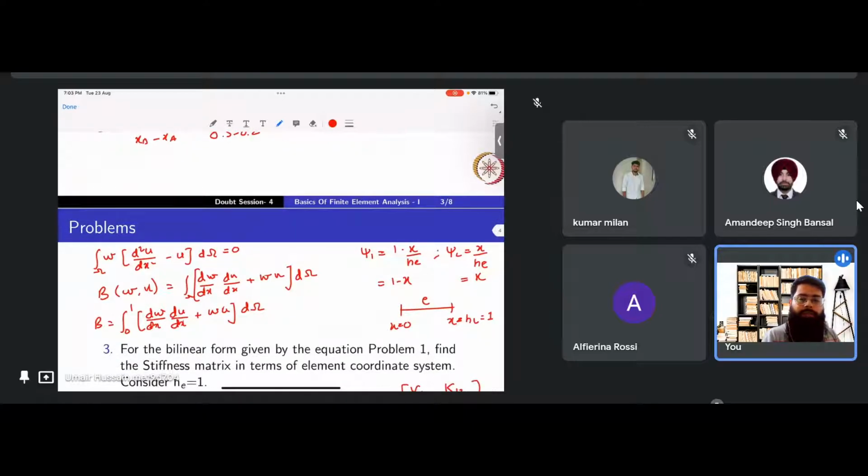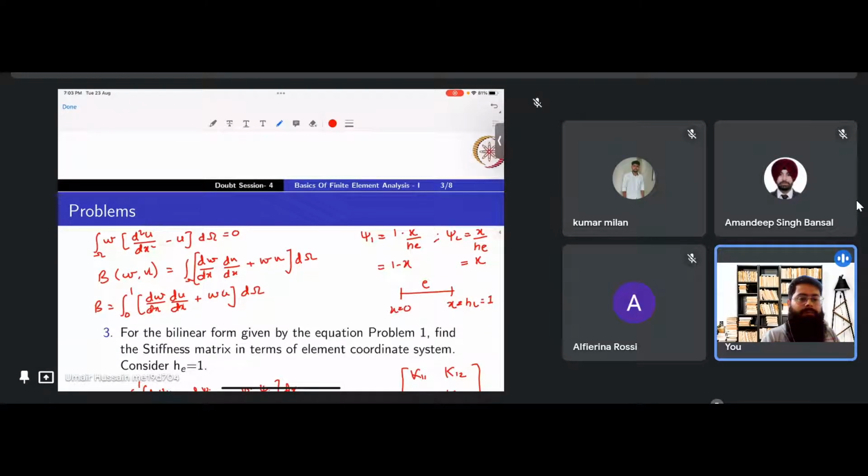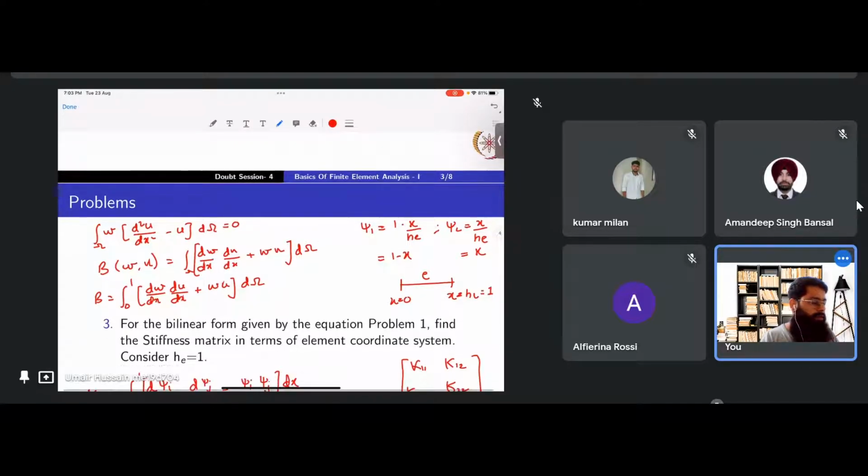If you observe, what we did in the Rayleigh-Ritz method, we're doing exactly the same. We're lowering the differentiability, and we are choosing the same function for the weight function as we did for the approximation function. So that's why I earlier told you that the way we solve it is not different in FEM. All of what we did is done, but now it's on specific domains, specific elements. We define these things. So that's why our approximation function comes out to be the same every time.